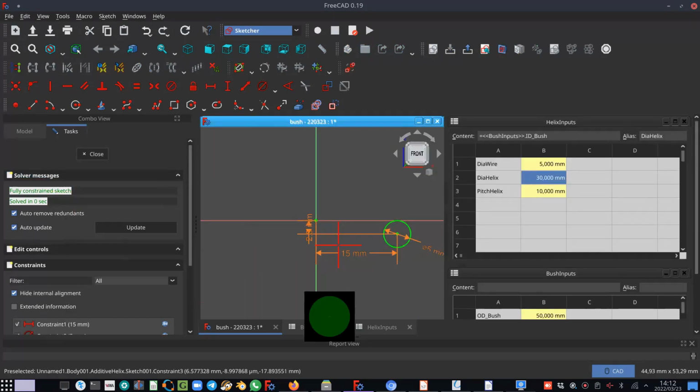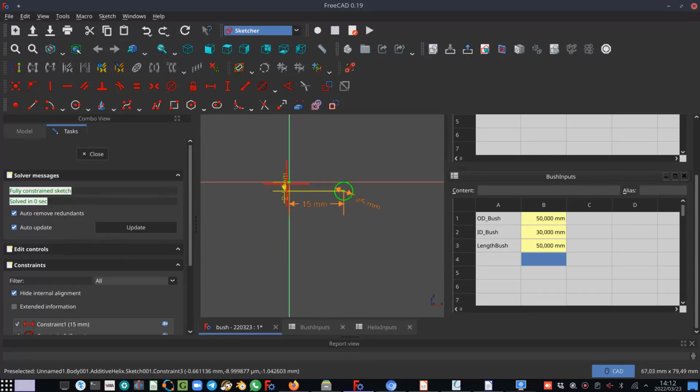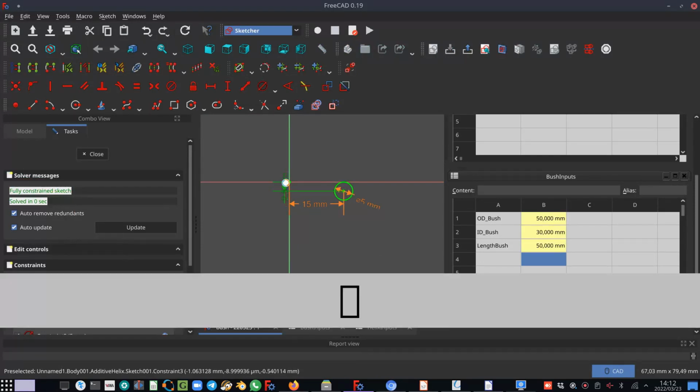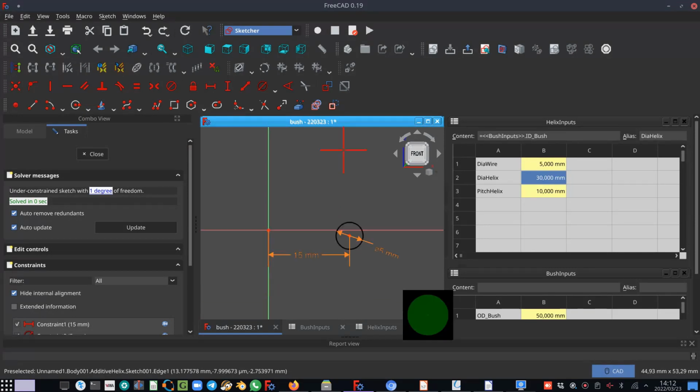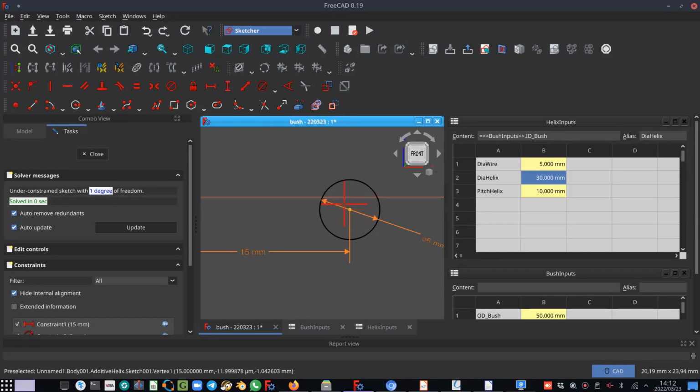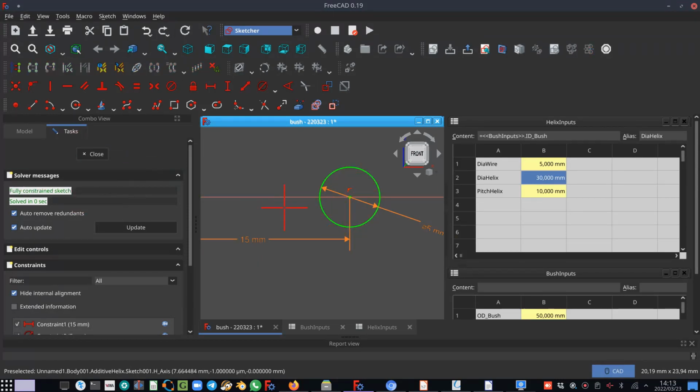And if we remove that dimension and we make it, let's click that icon, fix a point to an object, okay, and we click the center line and that axis, there we go, it's now fixed to the x-axis.